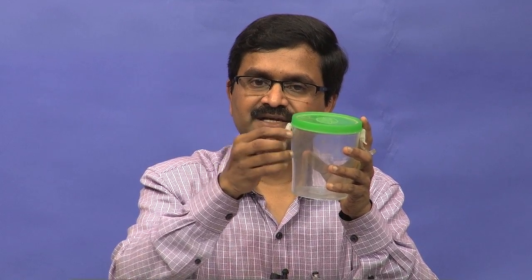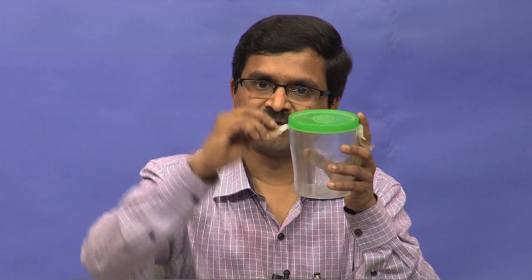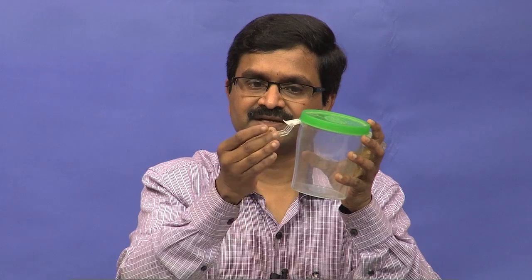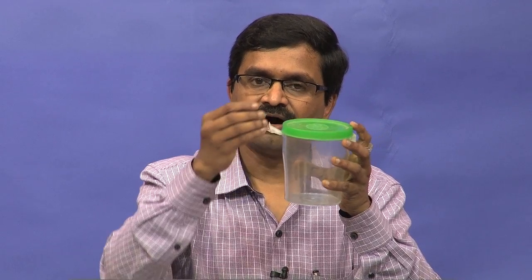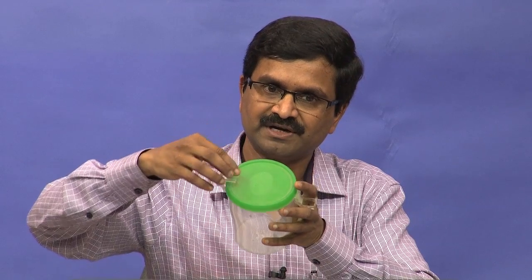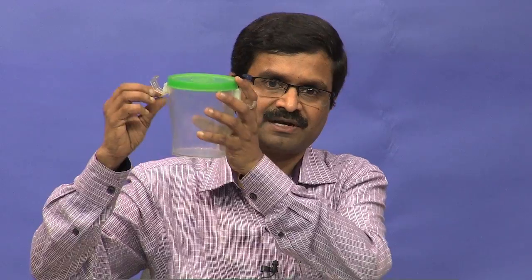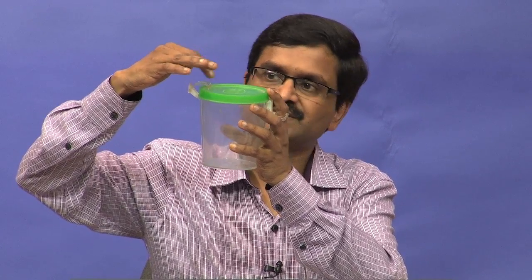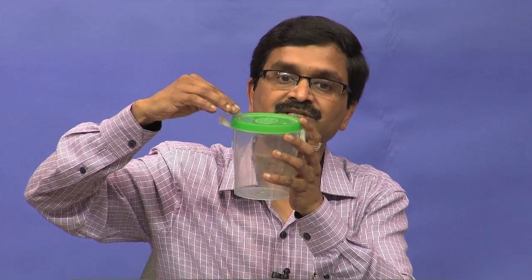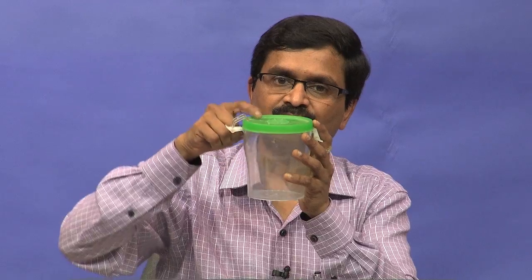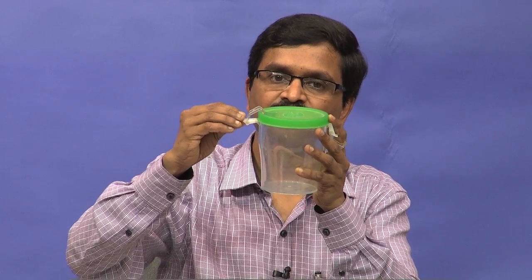If you look at this, there is a hinge here with the white one, that is why I am able to rotate, and with respect to this white one, this transparent one has another hinge. So, what we have here is an RR serial manipulator, but the moment I put it on top of it like this, it actually becomes a slider crank. When it is at the top, it is like a slider crank, because there are two joints and a slider and a slight rotation also here. And once this thing touches the lip of the lid, then it cannot move anymore, it becomes a structure.